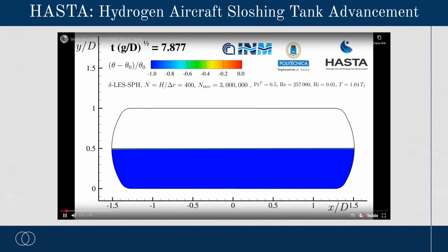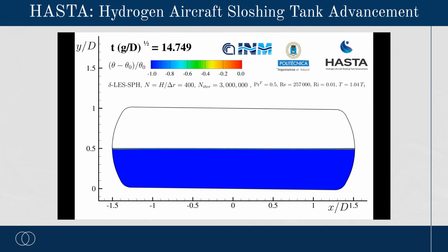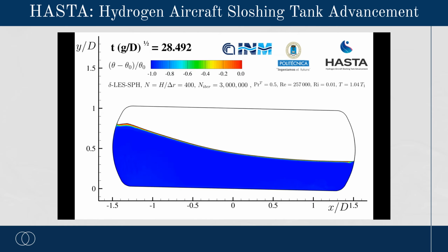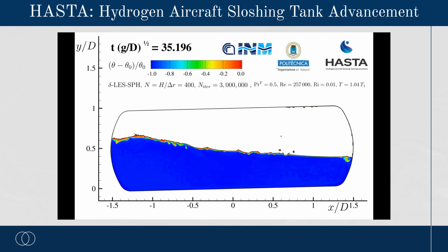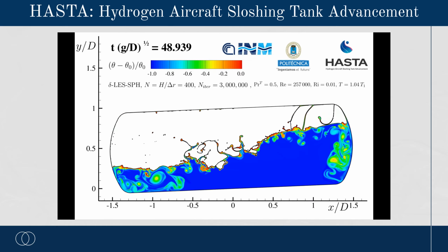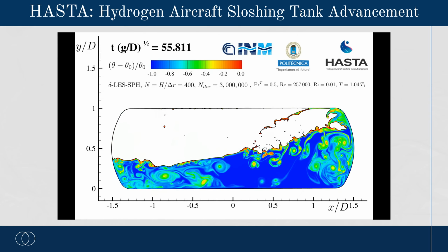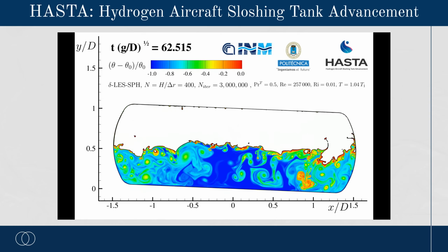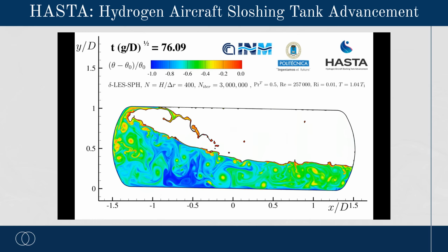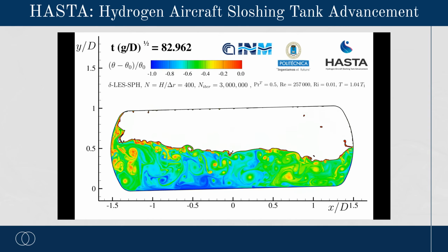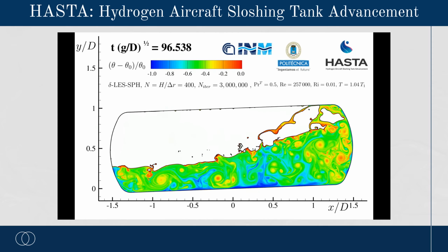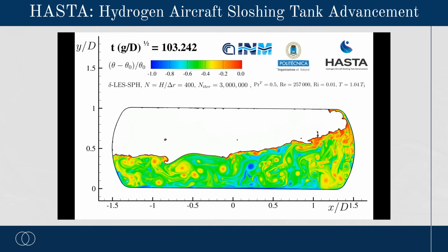Conversely, when the tank motion is close to a resonant condition, the gas is able to heat the liquid much more rapidly. As shown in this video, the violent liquid motion leads to the formation of thin jets and to the fragmentation into droplets. Both the jets and the droplets are heated very quickly, and when they impact the underlying liquid and re-enter the bulk, they act as an efficient mechanism for heat transfer.